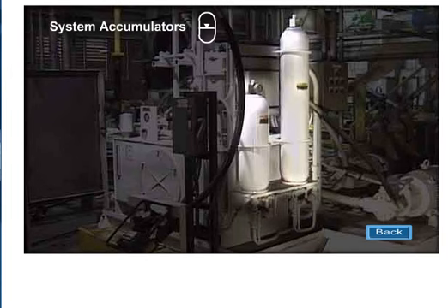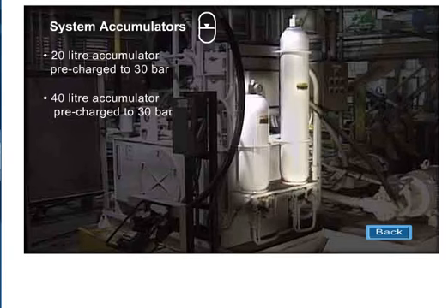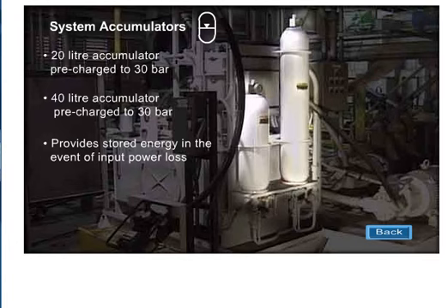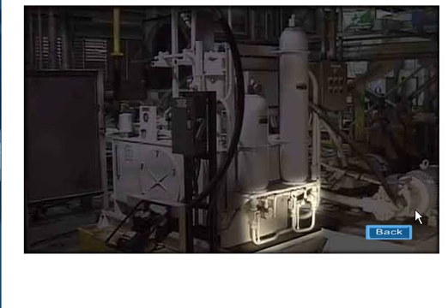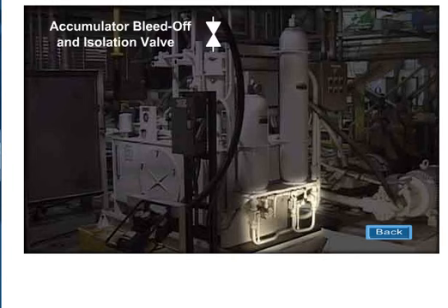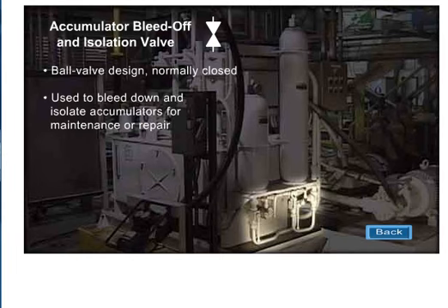System accumulators. 20-liter accumulator pre-charged to 30 bar. 40-liter accumulator pre-charged to 30 bar. Provides stored energy in the event of input power loss. Accumulator bleed-off and isolation valves. Ball valve design, normally closed. Used to bleed down and isolate accumulators for maintenance or repair.